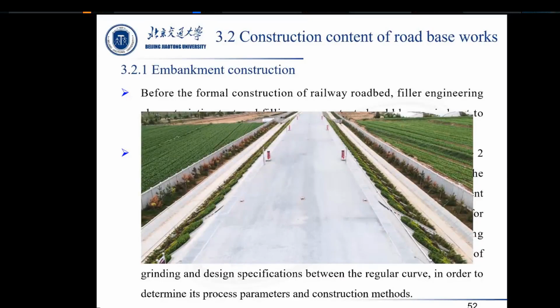According to the actual site conditions of the roadbed, choose 1 to 2 sections, with the width of the roadbed plus the width of the overfill and a length of not less than 100 meters, as the test site. According to the different types of fill, select different compaction machinery to carry out, below the sub-base, a layered filling compaction process test to find out the